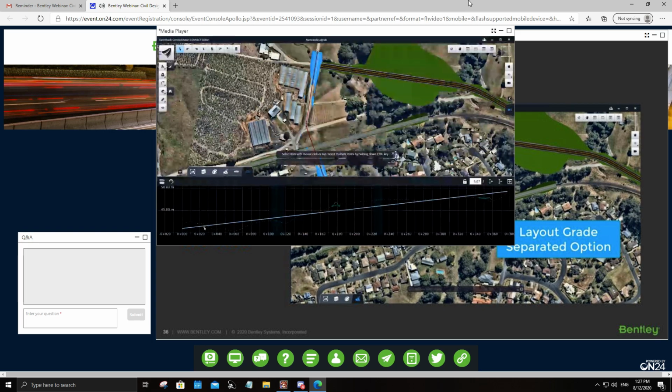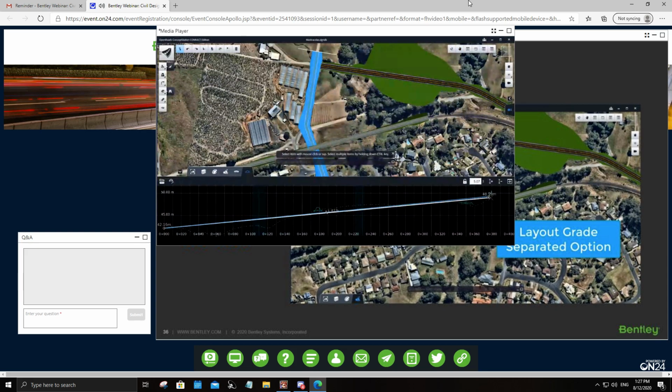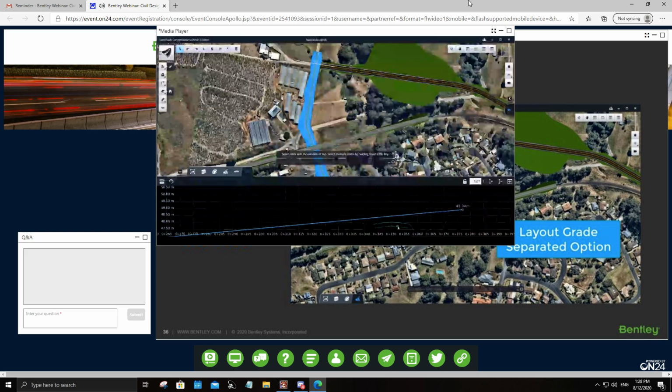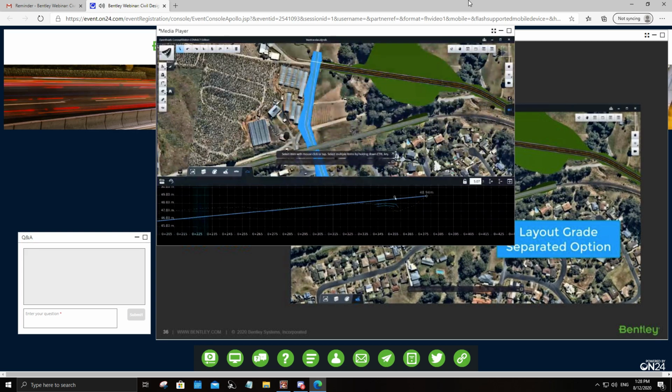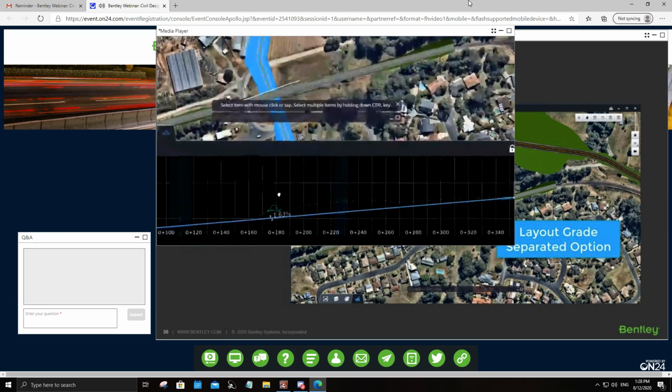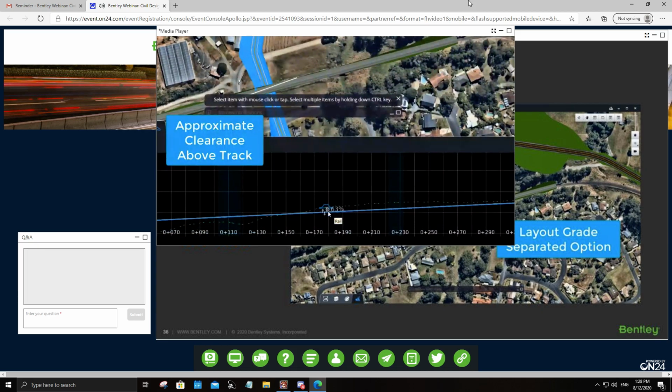Now notice how there's a need for us to modify our profile in order to tie into some existing roads, and also make sure that a bridge segment can be introduced just above the existing rail alignment or rail corridor. If you can see in the model, there's already a modeled corridor of rail station. With OpenRoads Designer, we also have a capability of modeling this type of corridor.